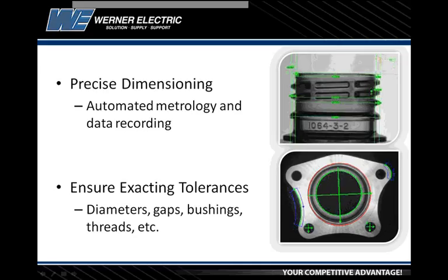So the company that manufactures the preforms is less concerned about the dimensions of the bottom part because that part hasn't been formed yet. But the threads are formed as they will be on the final product. So they can accurately gauge all of the critical parameters on that. And you can see they're even gauging the position of the threads. On the right it is higher than on the left, and because it's in the right position from part to part, they can check that as well.